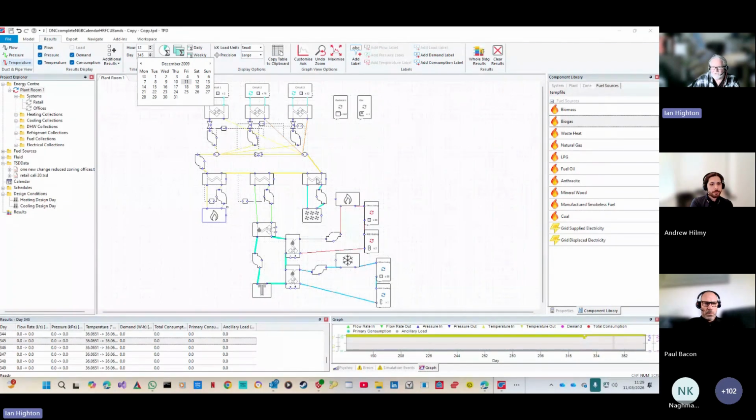So you'll try and do the dry air coolers first, then you'll try and use ground source, and if all of that fails, they'll then use the boilers. It's quite interesting actually, because we were lucky enough to get access to this building and actually go down into the basement and talk to the guys who were running the equipment.